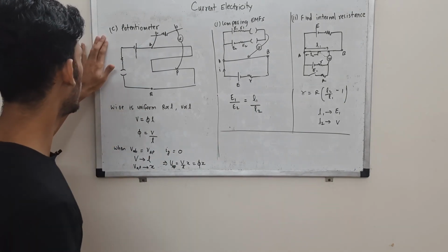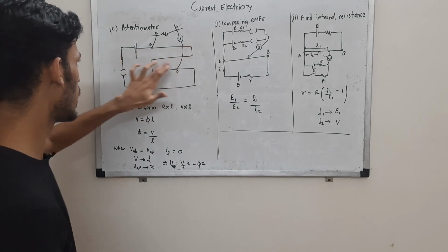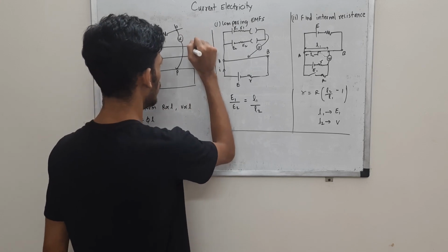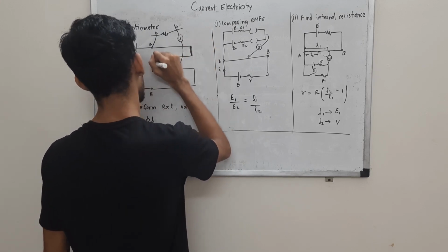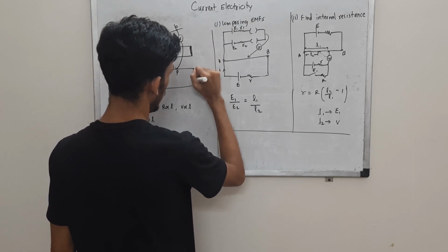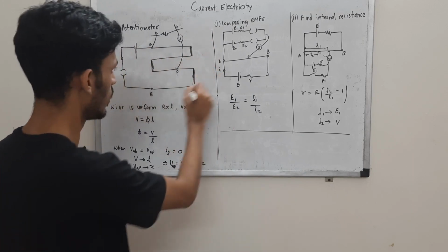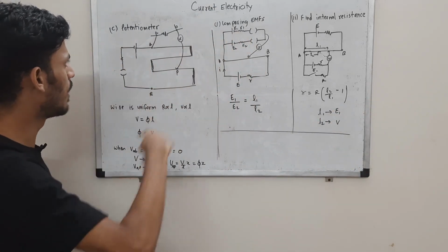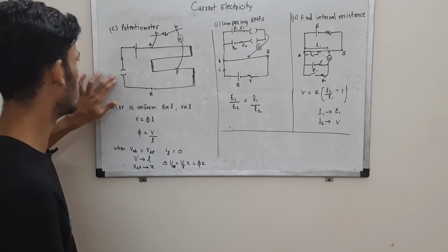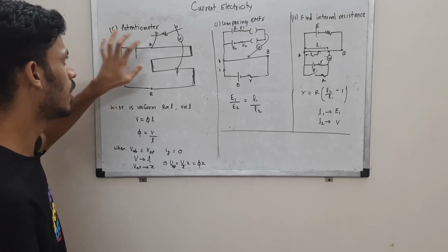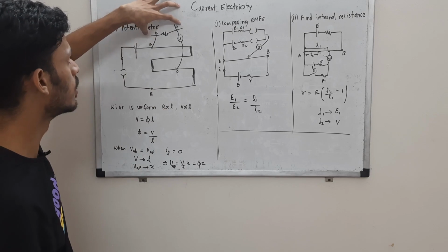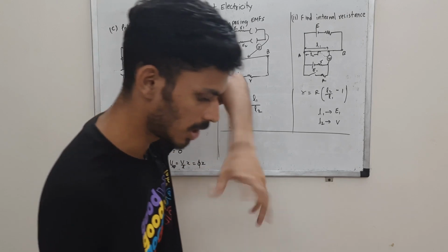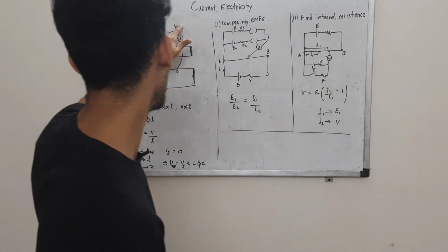So here we have a potentiometer, with this wire AB which is stretched out. These are usually metallic strips, so they do not contribute any resistance, and this is the wire running through them. You don't have to put it in one line, you can just wrap it around. Here we have a battery and a key you can plug in, and the circuit will be on. Here we have an element across which we want to measure the potential drop, the voltage between V and B.